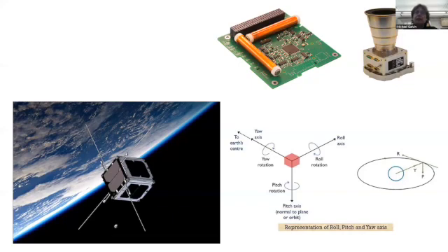So angular acceleration, angular velocity, and this is all usually solved for on a spacecraft as part of a Kalman filter of all of these different sensory inputs.